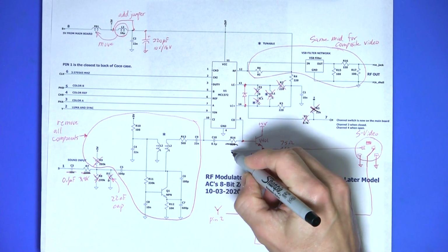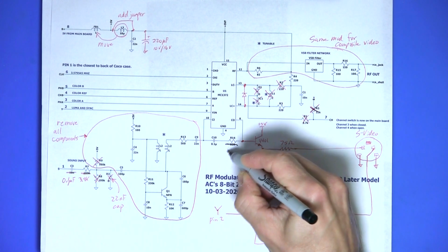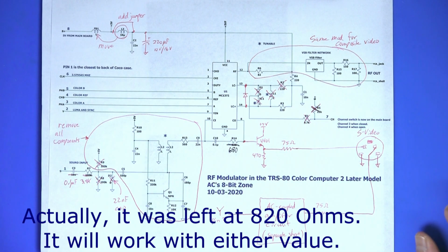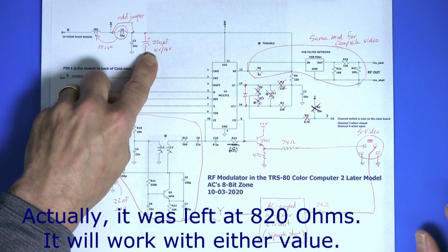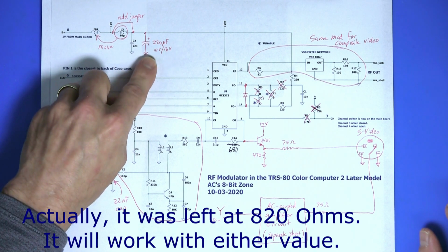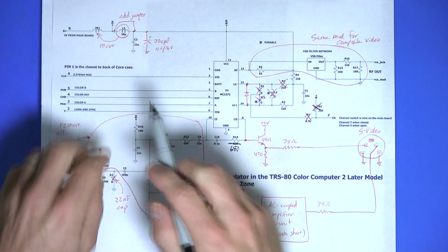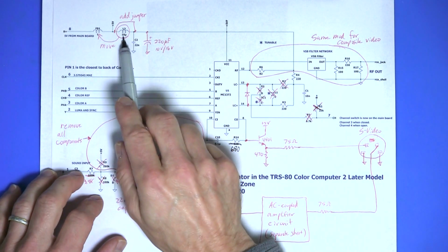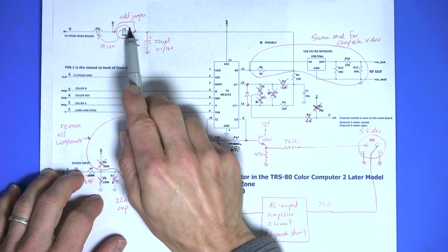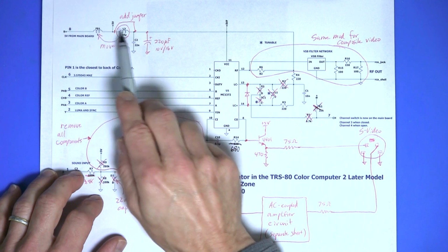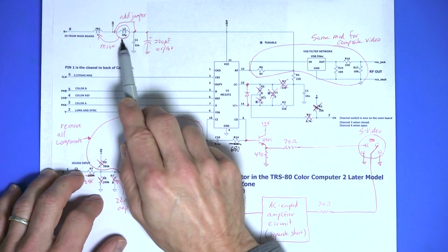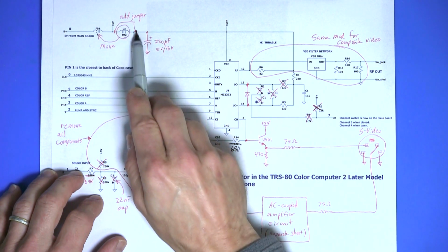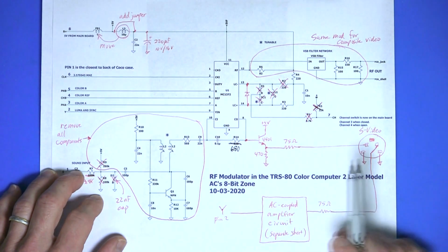I think this value has also been changed to 680 ohms. I just happened to notice that. And again, the addition of a bulk capacitor really cleaned up the waveforms significantly. And I'm showing here how I'm reducing down to a single inline inductor coil. So I remove this one and I move this component here, mainly because I can read the value of this one. I'm showing a 10 microhenry inductor, and then of course you want to jump over the old location of L3.